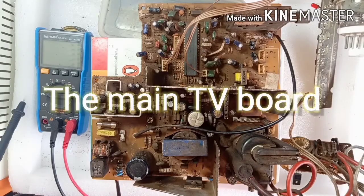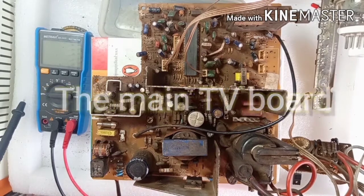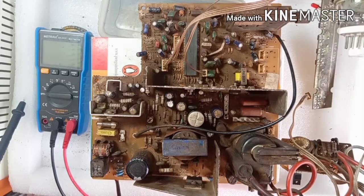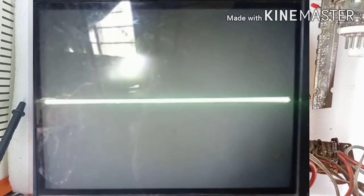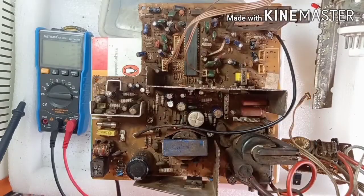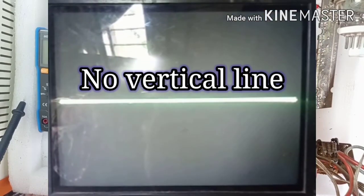Alright, we have the top view of the main board here. This is a pretty old circuit board. We see a horizontal line displayed on the screen, which tells me that the horizontal section is still working while the vertical section has gone bad, simply because we have no vertical line on the screen. This probably is due to a defective vertical IC.